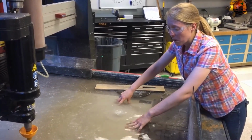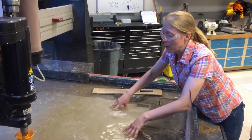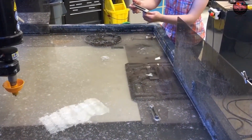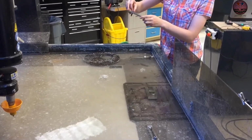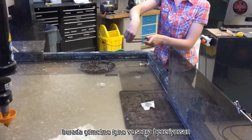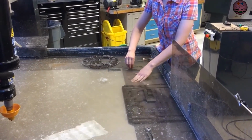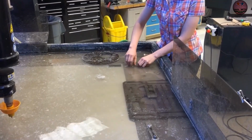When you secure a part, you need to make sure it does not wiggle at all. If it wiggles, it could possibly flip up and damage the nozzle. So this is one of the clamps I can use. It has 2 bolts. One bolt goes in this slot here, and then you screw that into one of the holes on this L-shaped piece. So I'll screw that in.